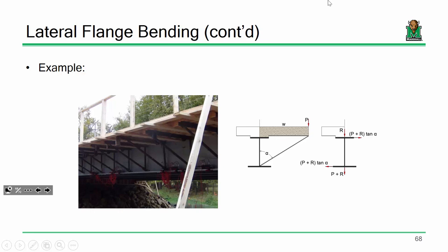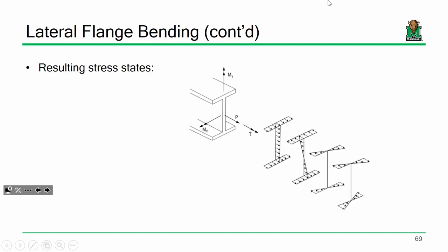Well, I've got all this wet concrete and this applied screed. This is from the Bidwell and what have you. It's going to, keep in mind this is acting eccentrically. It's going to want to twist that beam, right? Make sense? So I propose that when you twist that beam, you're going to get some additional stresses in the flanges. They're going to look something like this.